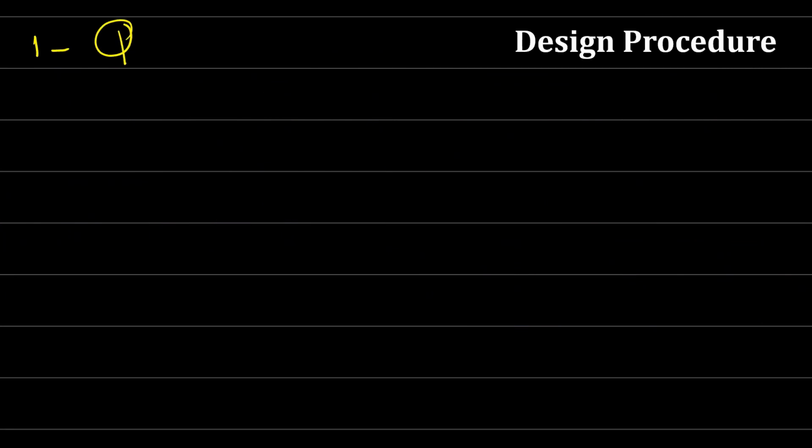Now for small values of Q, we have higher boost gain. So we can achieve higher boost gain, but the response to the frequency modulation in the above resonance region is low. Now we'll see how this can be translated on the figure. You'll find we have a small range of frequencies within a high range of gain. So this sometimes makes problems, sometimes it's okay. So we'll see this now.